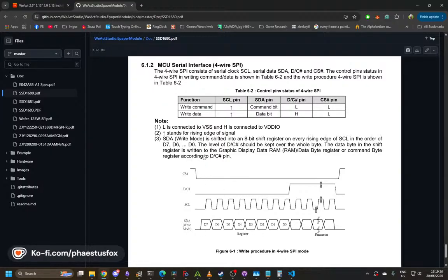This is SPI, which is similar to I2C, but SPI is significantly faster, but you have to dedicate a wire to every device you want to talk to. So with SPI, you have to pull chip select low, and that means I'm talking to you, and then you can talk really fast down the line. Whereas with I2C, you have to pull the line low, then send your 7-bit address, and then if there's someone on the other end, they will start listening because that was their address, and then you send the data. Whereas SPI is I pull it low because I know that you're the one on the other end, and then you can share the actual clock and data bus.